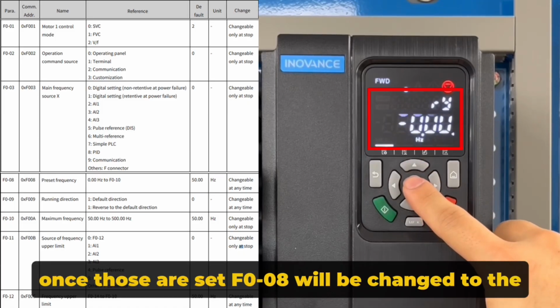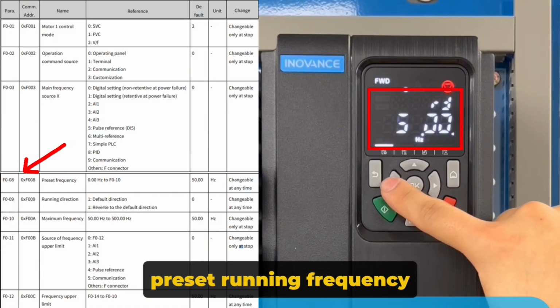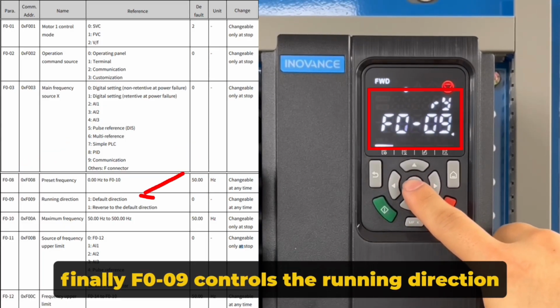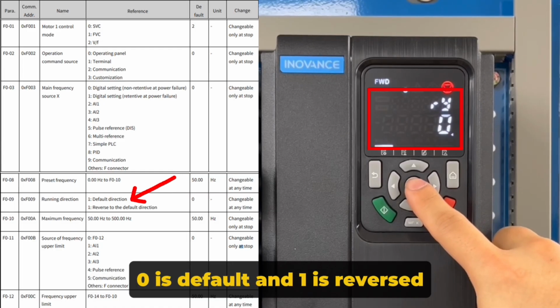Once those are set, F0-08 will be changed to the preset running frequency and can be changed at any time. Finally, F0-09 controls the running direction, 0 is default, and 1 is reversed.